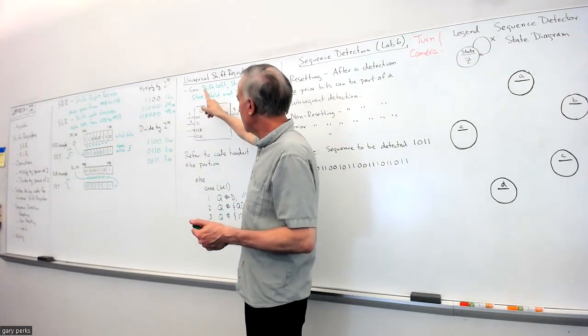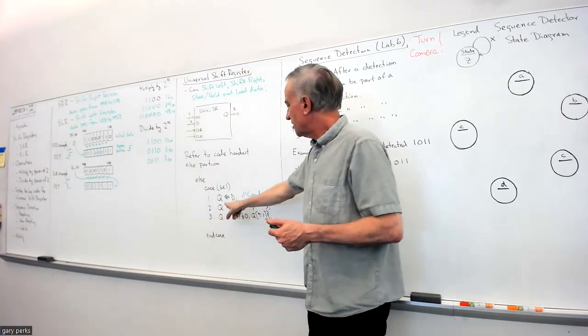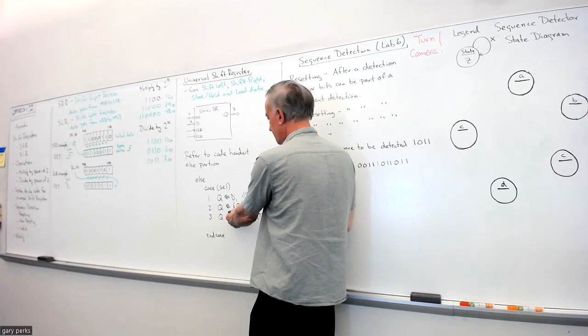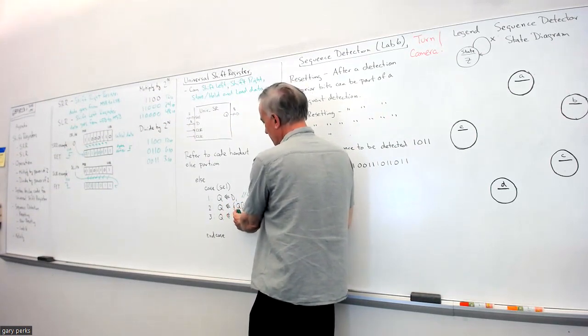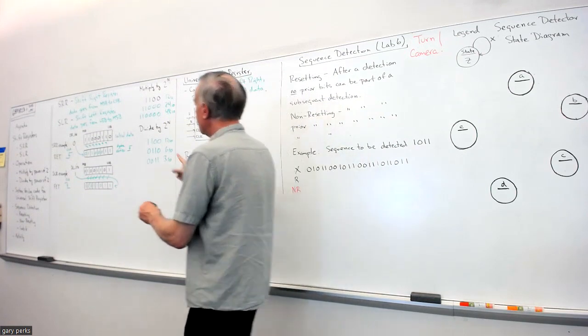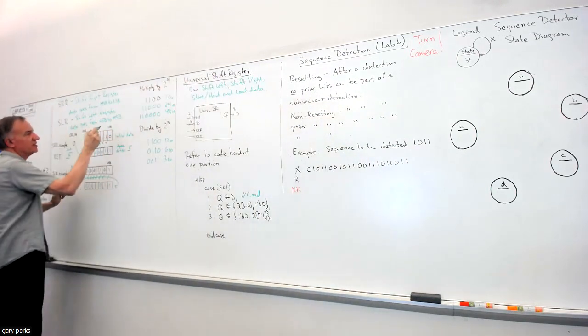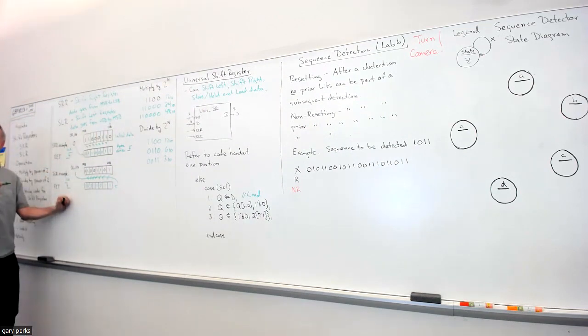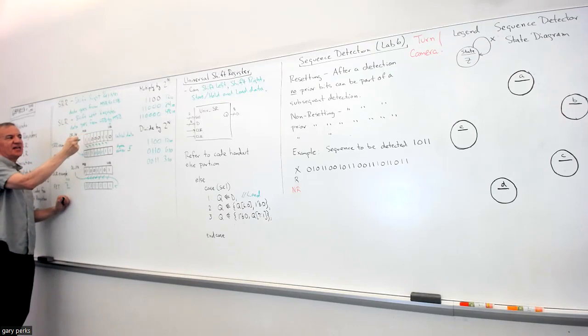Okay. All right, but let's look at the next line of the case statement too. So when the select line is a 2, binary 10, Q is going to be assigned what you see here in braces. And look what's inside these braces: Q[6:0]. So remember that we give the least significant bit number 0, and this is 8 bits, so the most significant bit would be number 7.